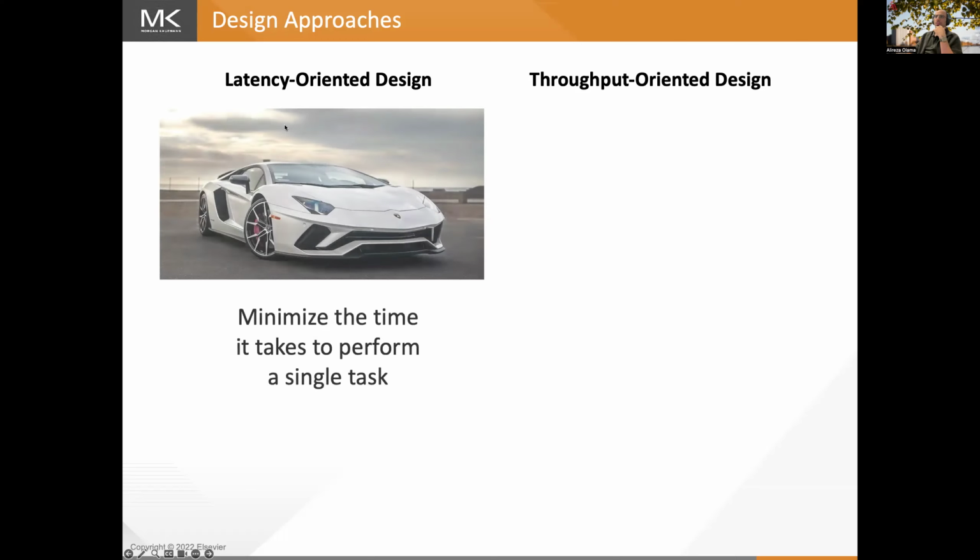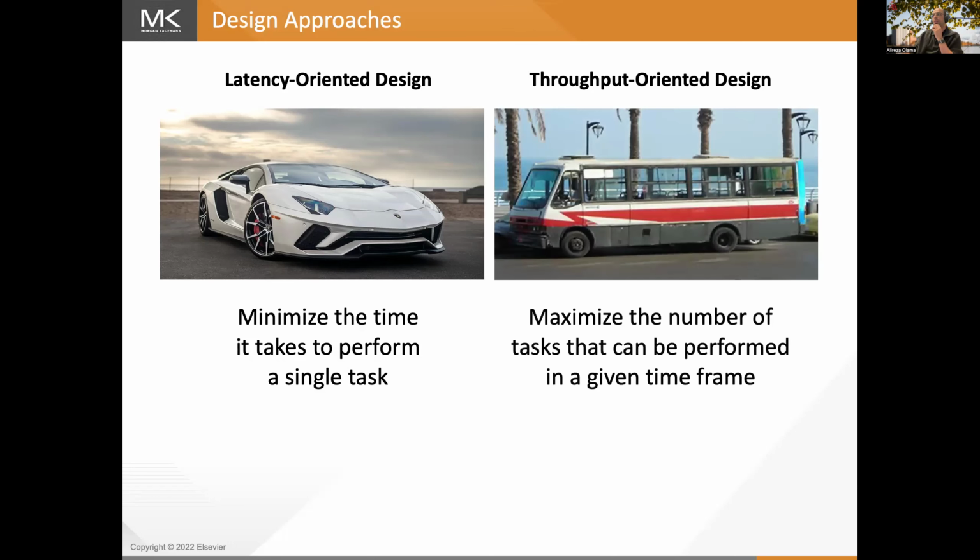When you have a latency-oriented design, what you care about is to minimize the latency, right? So you want to minimize the time that it takes to perform a single task. And on the other hand, when you have a throughput-oriented design, you want to maximize the number of tasks that you can perform given a time frame, right? So these are different design approaches for building processors.